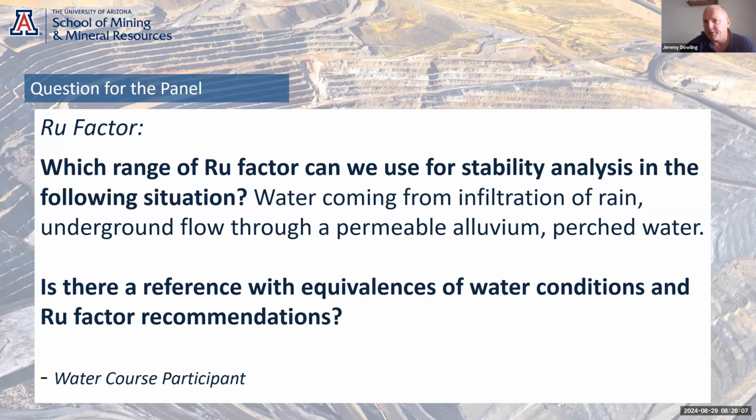So on a few projects we've worked on with the geotechnical teams, we've used a sensitivity-based approach where we've had a three-dimensional flat model or deformation model, implemented the regional groundwater system with deep piezometric data and a calibrated groundwater flow model, and then the excavation damage zone or the shallow transient groundwater that's more uncertain, we've put a range of RU values into the geotechnical model from 0 to something fairly conservative,